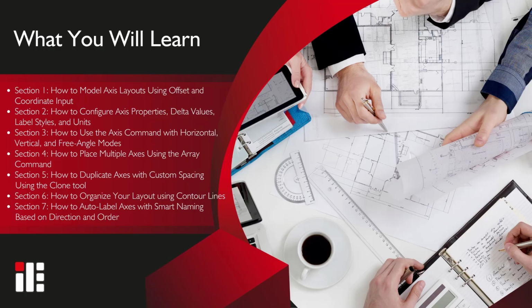In this video, I'll show you how to create and manage axis grids for an industrial-type steel building in ideCAD Structural. It's important to note that the axis command works exactly the same in architectural, reinforced concrete, and structural steel projects, so once you master it, you can apply it across all disciplines in ideCAD.